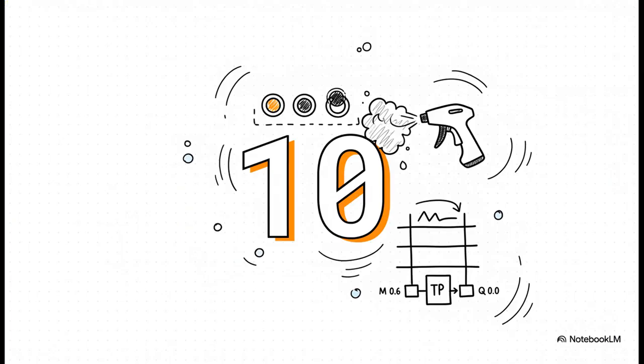We've meticulously counted the presses using our memory bit sequence, so let's guide the system to the climax of the logic, where that final press actually activates the hardware. 10 seconds. That's the exact preset value we need for our sanitization spray to be effective. When that final memory bit M0.6 goes true, indicating the fourth press, it triggers a timer block. Specifically, we're using a TP or timer pulse operation. We set the preset value of this timer to 10 seconds.